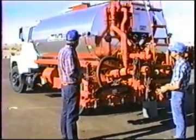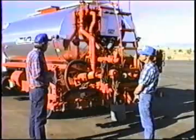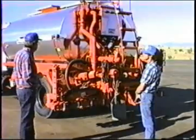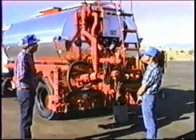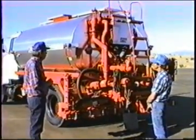Now, if for some reason we ended up on the job with the tank full of hot asphalt and the spray bar wet, then we've got an even worse situation, because if we circulate that wet spray bar into the tank, it's going to push the water that's in the spray bar into the bottom of the tank. Worst place for the water. It's going to boil out, and we've got a terrible mess.